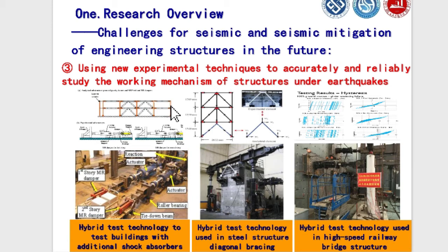Then we obtain the structure's response, and we input it to the controller to control the actuator to give the displacement of the damper. In every time step, we realize the force balance and the boundary between the numerical substructure and the experimental dampers.